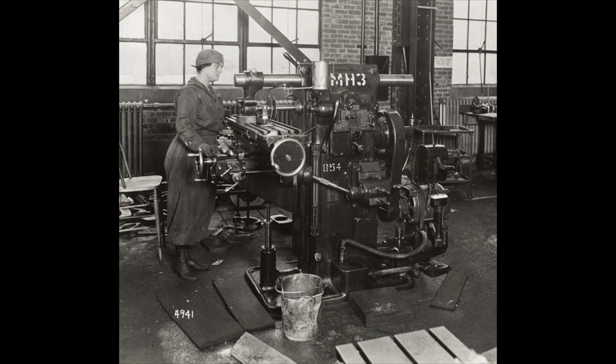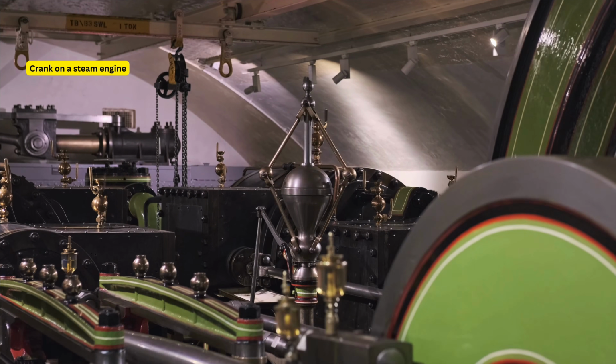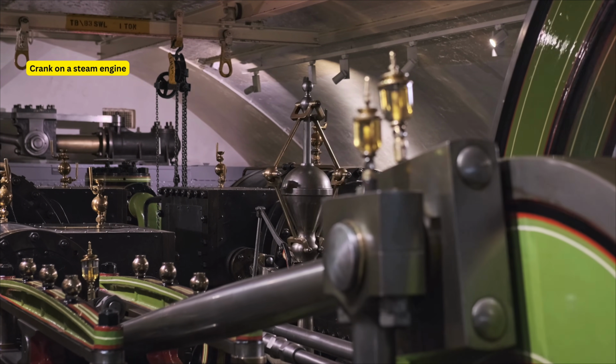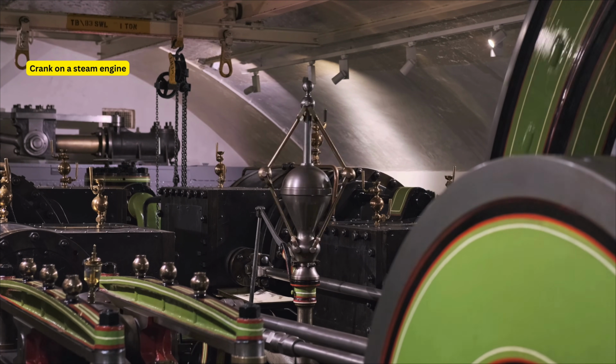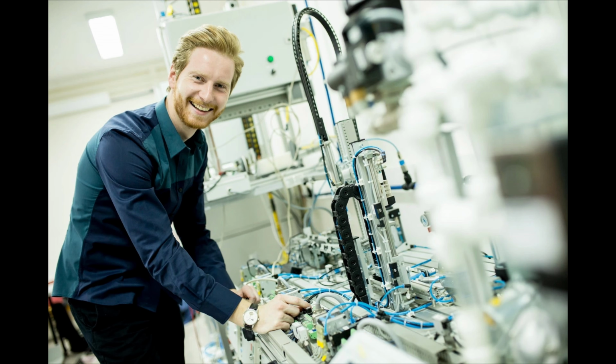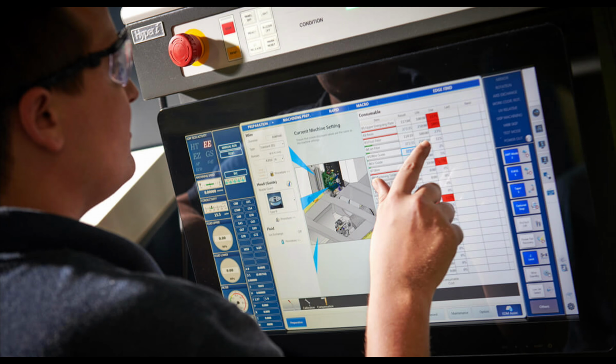It's not that one is better than the other. Each has its own set of advantages. Cams are chosen when failures must be predictable and gradual. If the environment is harsh, heat, vibration, or radiation, and you want little or no dependency on electronics, then cam-based or other mechanical memory is better. If your system can tolerate a non-deterministic failure and redundancy and diagnostics are available, then software solutions may be better. When a cam wears a bit, it can still perform, just worse. If there is a software glitch, a controller can crash and stop everything instantly.